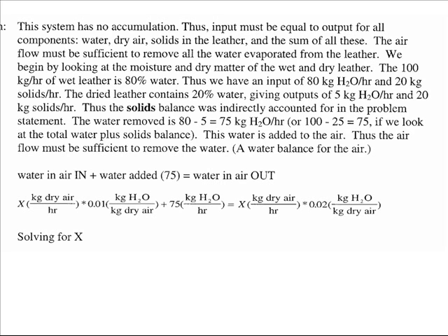That is to say, the solids do not evaporate. They do not change the stream. They don't go into the air. The solids that come into the problem are going to have to be the solids that leave the problem. And because we know that there were 20 kilograms of solids that came into the problem, there also have to be 20 kilograms of solids that leave with the dried leather.